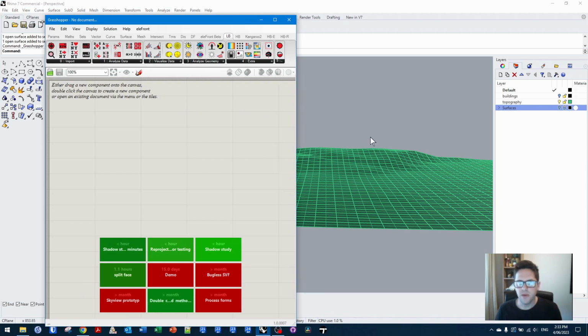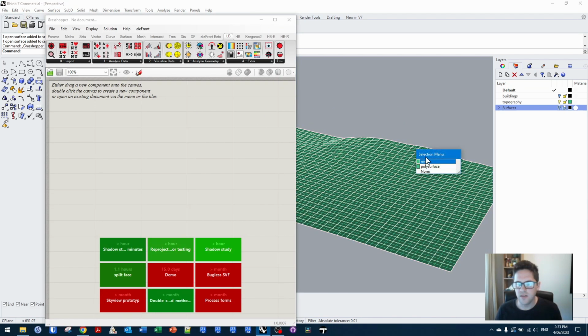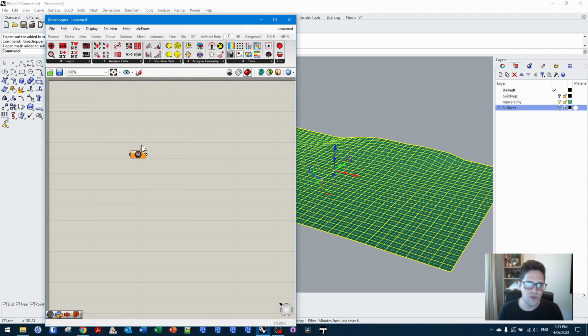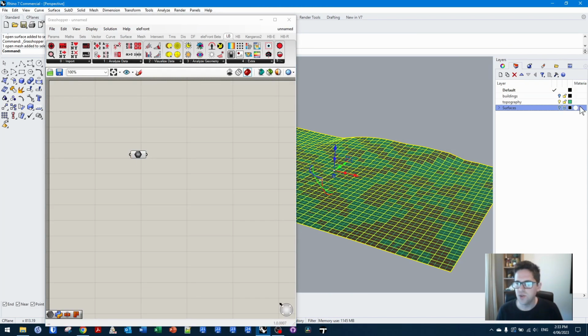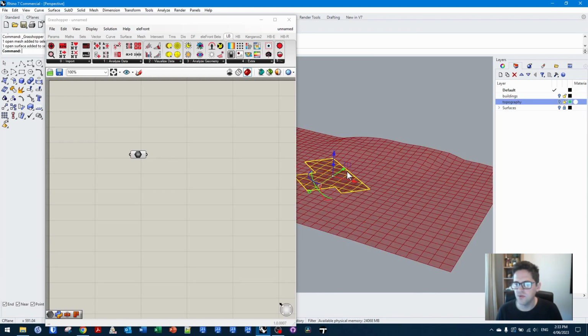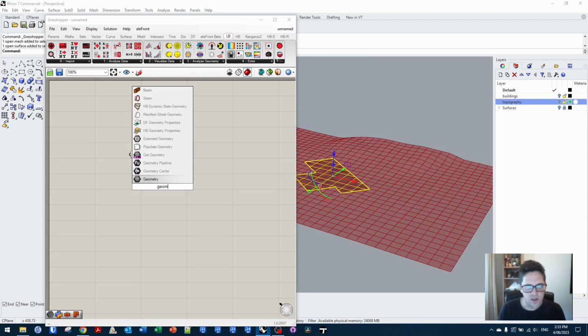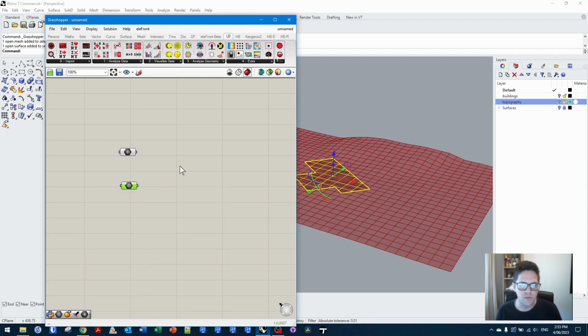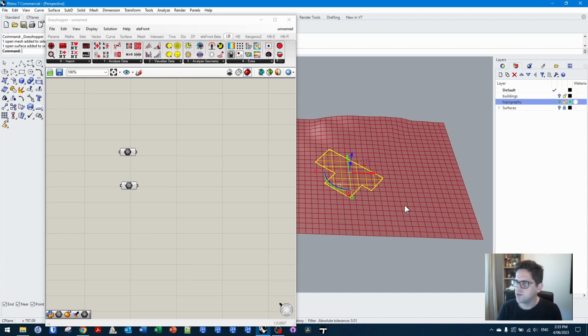And in Grasshopper, we're obviously going to be taking two things in this case. First of all, I'm going to take the mesh surface. So I'm going to just make a mesh. Just store the mesh, turn off the ground, so we can just grab also our testing object. So we're going to try and basically turn our testing object into a tiled surface where the center of every tile is a testing point.